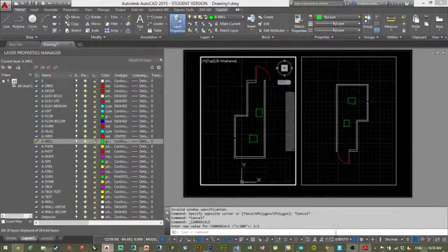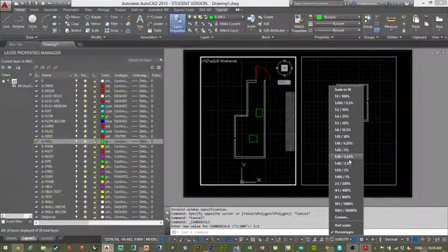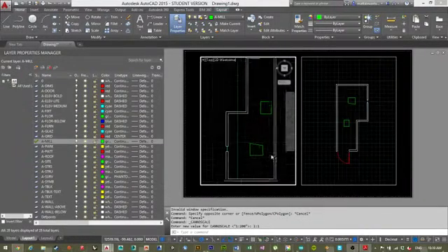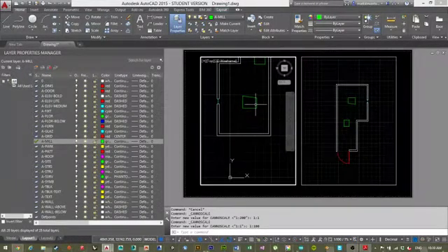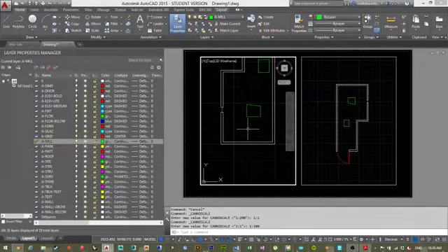Right. So if we wanted this at 1 to 100, that dimension is not set up to show. That might seem bad, but usually you would set things up so you do all your dimensions for your overall drawing, and then if you zoom in somewhere, like a corner on a wall, and do a detail of that wall, you wouldn't want to redraw that.